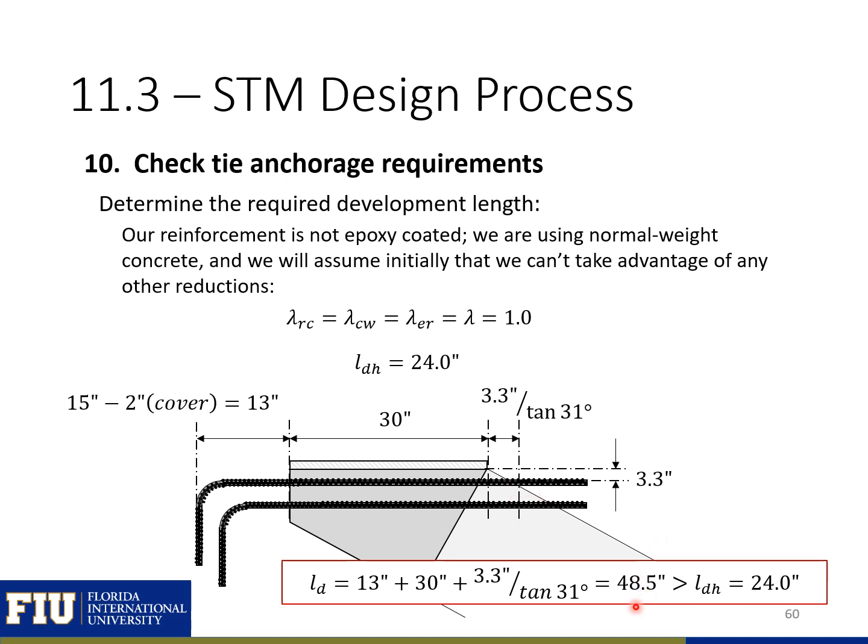So you can see that our available development length is 48.5 inches, and this is greater than our required development length for the hook of 24 inches. So we know we have sufficient development length for our hooked bars here.